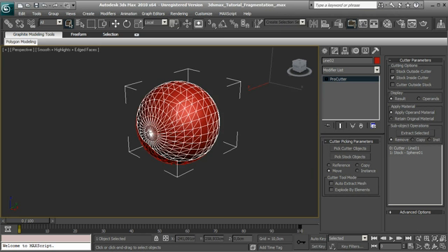You can use, for example, more splines in the same way. So you can create the sphere, you can create all the cutters, and you can select the sphere, select ProCutter as compound objects, and then you can select all the cutters. So with a multi-selection, you can break the mesh just using the ProCutter one time. But I'd like to show you how you can decide step by step how to create the breaking pieces.